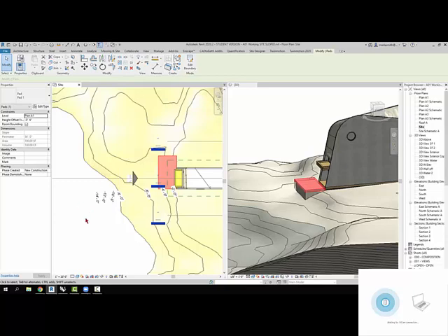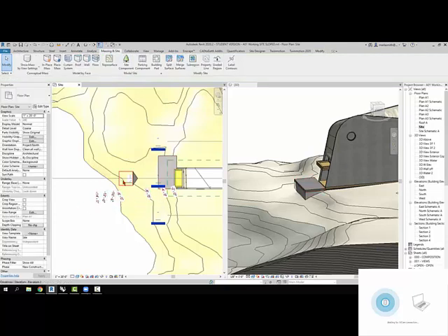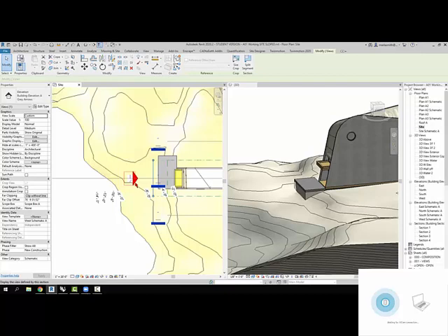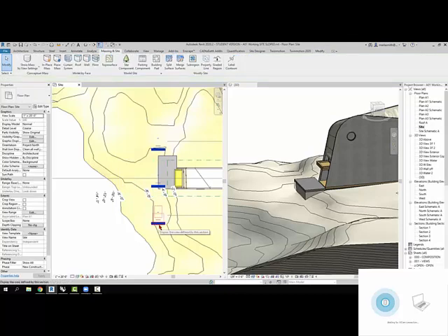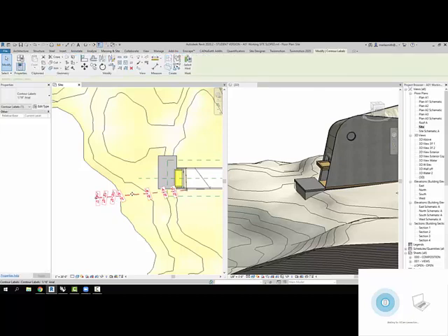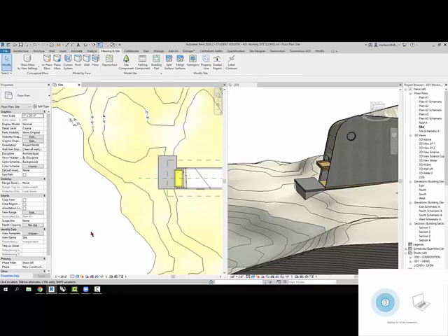A lot of this stuff is in my way, so I'm just going to turn it off. I'm just going to pick this elevation in VH, and also the sections VH, just to get them out of my way, and this topography line seems to be following me around, so I'm going to move it. So now I want to make some stairs that go down.